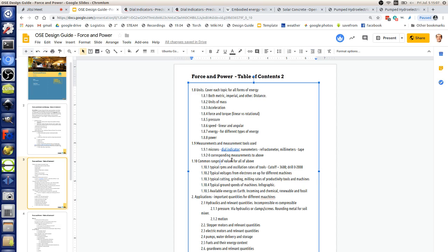When you think about it, an electric motor, well, that's 3,600 RPM. A wheel on a car may be like 500 RPM. A slow-moving tractor may be like 10 RPM or something. Those numbers you have to know, because when you buy a hydraulic motor, you look at its RPMs. For a wheel hydraulic motor, the max RPM may be like 150, which gets you to like 10, 20 miles per hour in a common situation. When you're sourcing parts, you need to be familiar with that enough to predict its performance, and so you have to calculate those kinds of things.